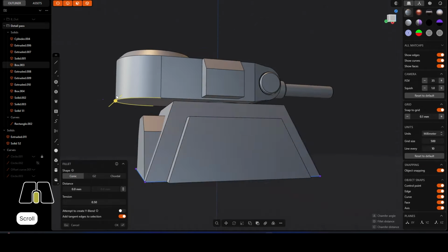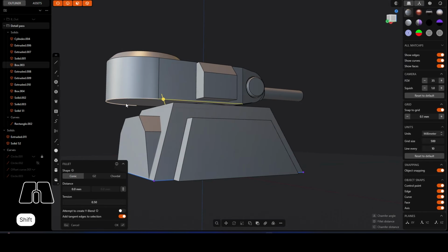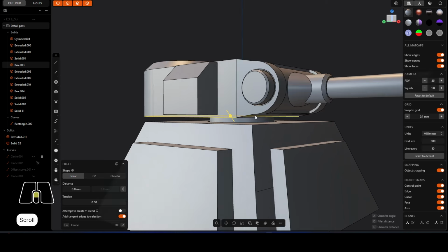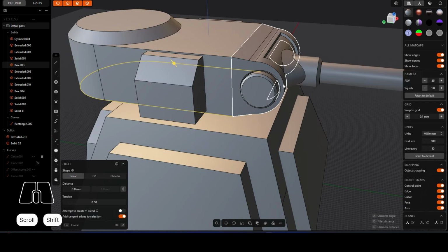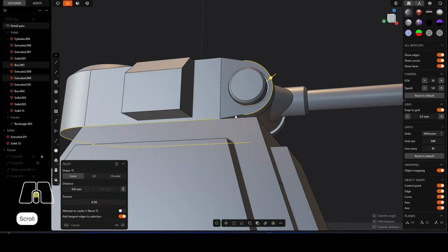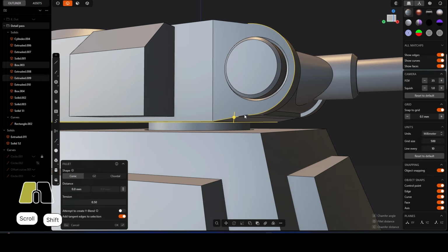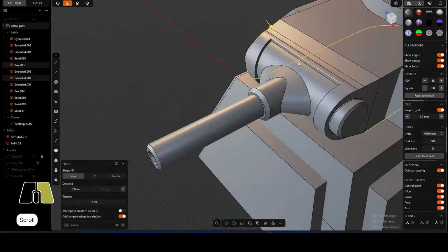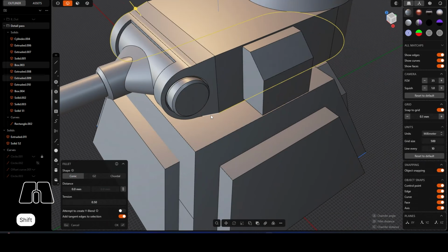Similar to the bottom here, you might want to grab it, and what we can do is maybe grab these pieces here, and we can see what we get. I could even grab maybe this point. So if you're struggling, just use the number 2 key or click up here, and this allows us just to grab all these edges. What I've not done on this bit as well is I've not removed any redundant topology, so I need to do that as well at some point. So we can then grab these edges now, like so.